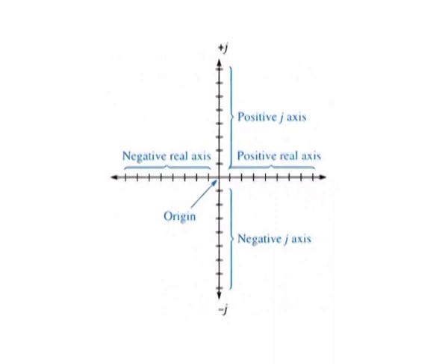In electrical circuit work, a plus or minus j prefix is used to designate numbers that lie on the imaginary axis in order to distinguish them from numbers lying on the real axis. This prefix is known as the j operator. In mathematics, an i is used instead of a j, but in electric circuits, the i can be confused with instantaneous current, so j is used.